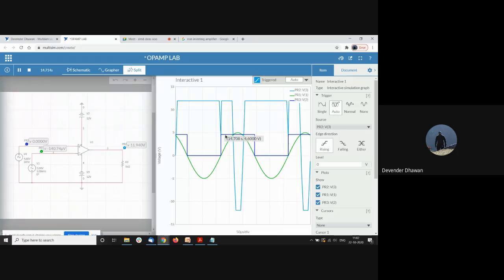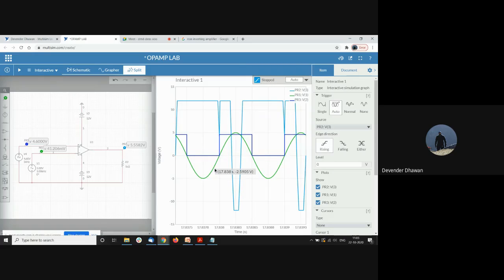But if you see now, the reference voltage here is 4.6 volts. Okay, and our signal is already less than that, so it will keep on remaining on the positive side of our saturation. So there is no transition on this point. Actually, there was a transition because our input was going over the reference voltage, but in this case our input is not going over the reference voltage. That is why there is no peak at this end. Okay, so this is one thing.